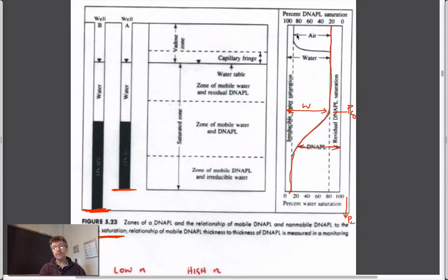And actually in this upper portion, the remaining portion that isn't either filled with the DNAPL saturation, this is the smear, if you like, right? This is the smear because it's had a pressure larger than the entry pressure at some stages. It's been loaded from the top, and it's been able to leave a smear as it's gone down. And only below this magnitude here does this smear become something that's larger than the irreducible saturation of this DNAPL. And so that's what the distribution would be if we saw it.